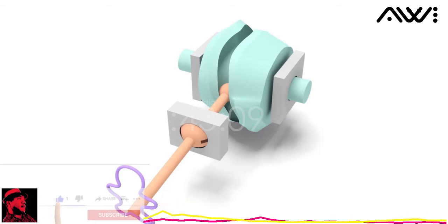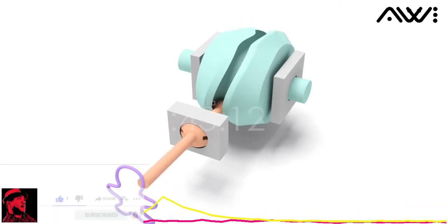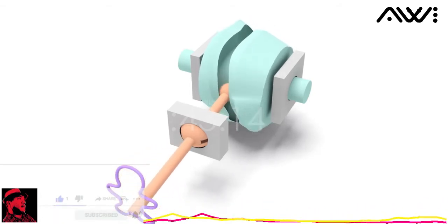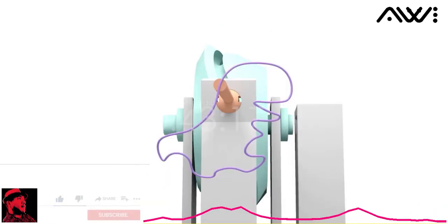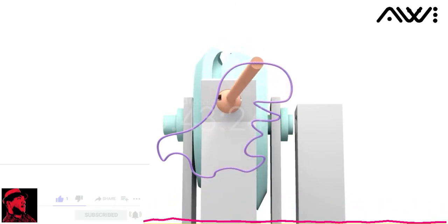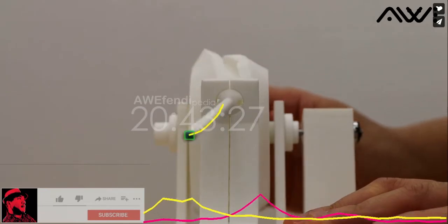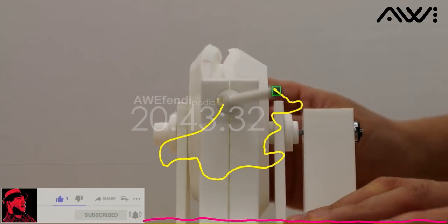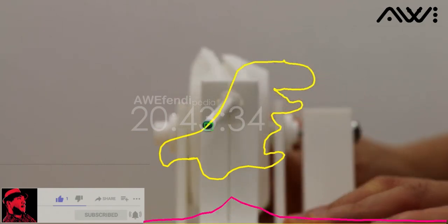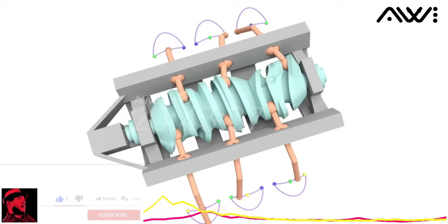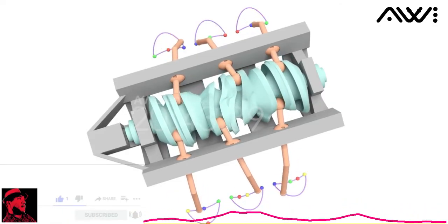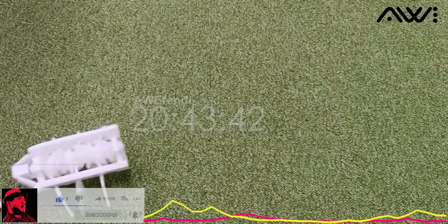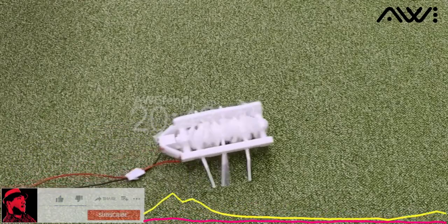We present a new kind of cam follower mechanisms that can exactly realize 3D trajectories specified by users. We propose a computational approach to modeling and designing these mechanisms, and verify their kinematic performance with 3D printing. By using our approach, we are able to design and 3D print a robot that can walk following a user-specified gait.